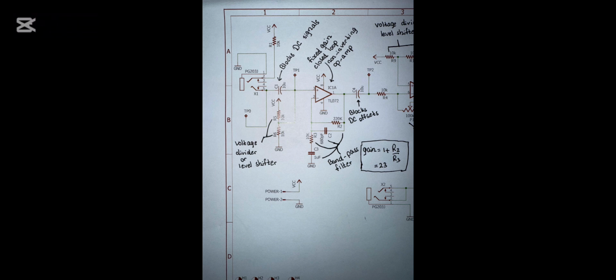Stage 1 is the preamplifier stage. The microphone in the stethoscope picks up the biosignals and converts them to electrical signals. As is the nature of biosignals, those signals are very weak, often just a few millivolts. So we need to preamplify those electrical signals to be strong enough for further processing. So in this stage 1, we are going to preamplify those electrical signals.